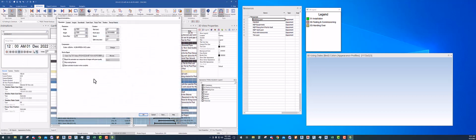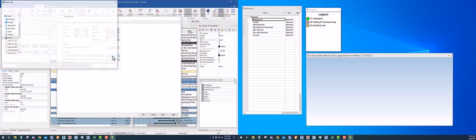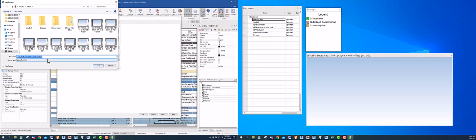Okay, now we want to export it. So right click on this animation, there is an option called export animation. When you click here, a window will come. It will ask you what will be the resolution, what will be the duration, which will be the file for export, everything. Click on browse to say where my file will be saved and what will be the